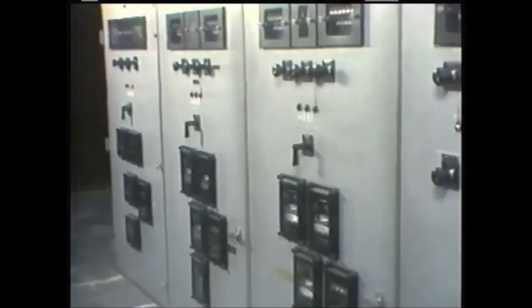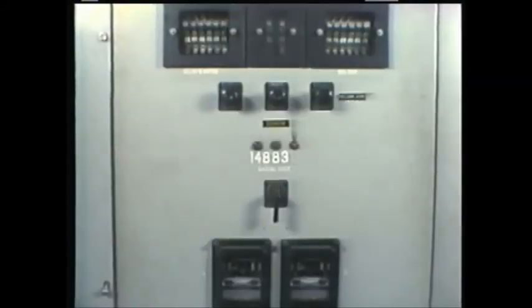Circuit breakers and fuses are just 2 of the many protected devices used in distribution systems. In the next part of the program, we'll look at some other types of protected devices. But before we leave the topic of circuit breakers and fuses, let's review some of the points we've covered. We said that circuit breakers are basically automatic switches that can interrupt the flow of electricity through a distribution feeder. Circuit breakers have the capability of opening and closing automatically, and when used as part of a coordinated protection system, they can operate in a number of different modes.